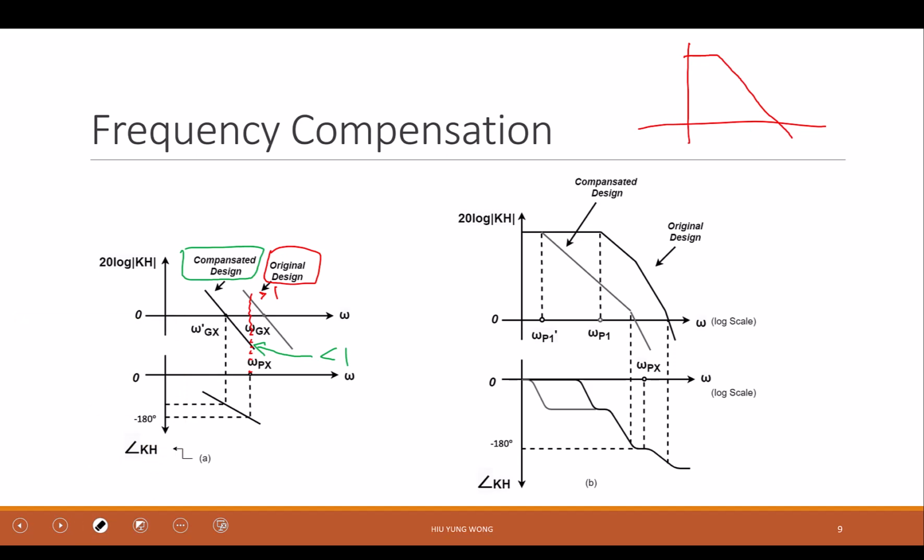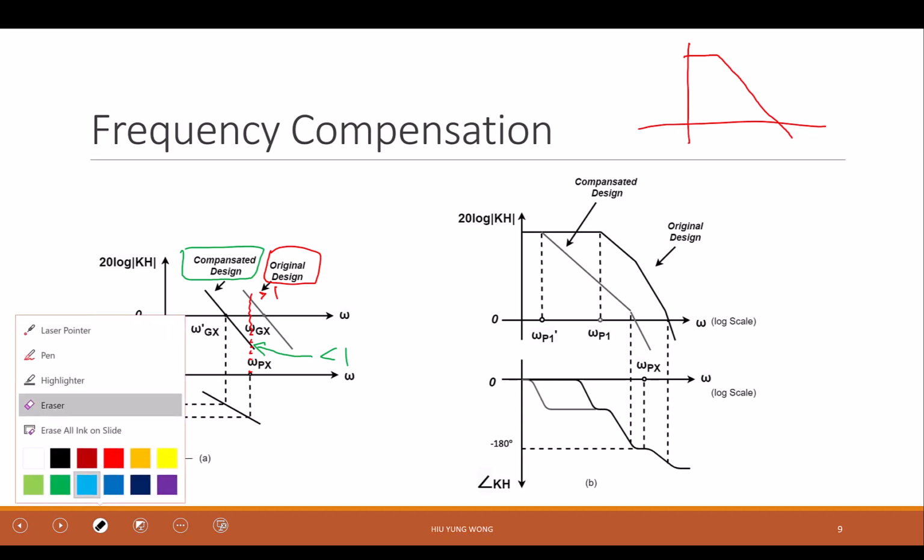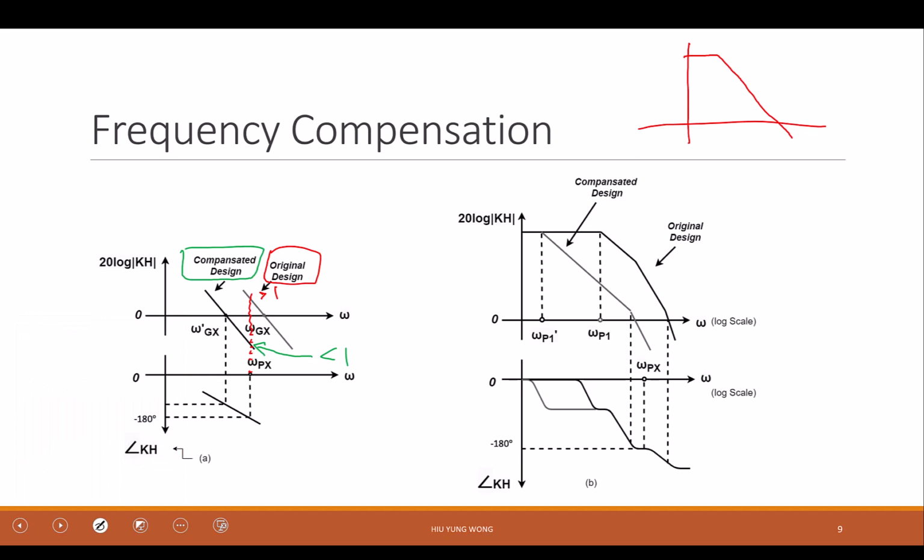By just looking at this figure, how can I reduce the gain without changing the phase? So he said, move the pole. But if I move the pole, isn't it that the phase will also shift to the left? The phase crossover. Yeah, but you are there actually. You are there. But because what I'm challenging you with is a single pole system.